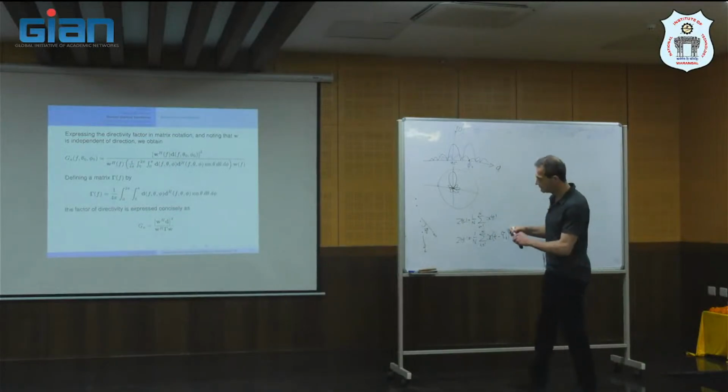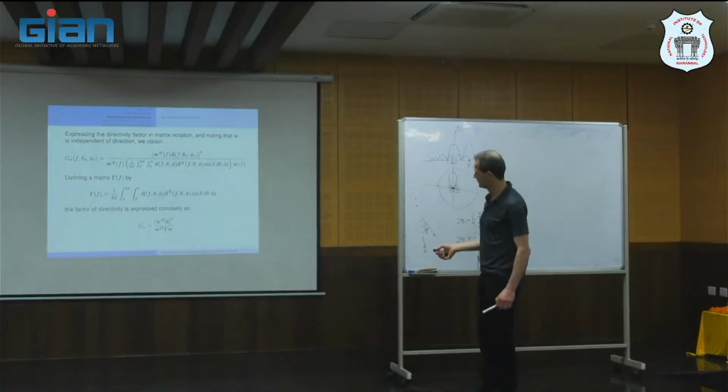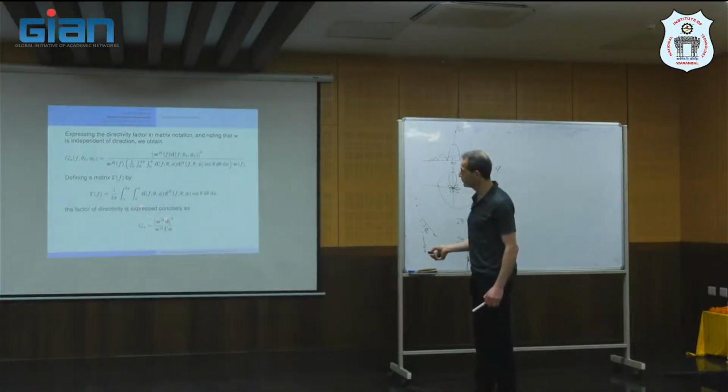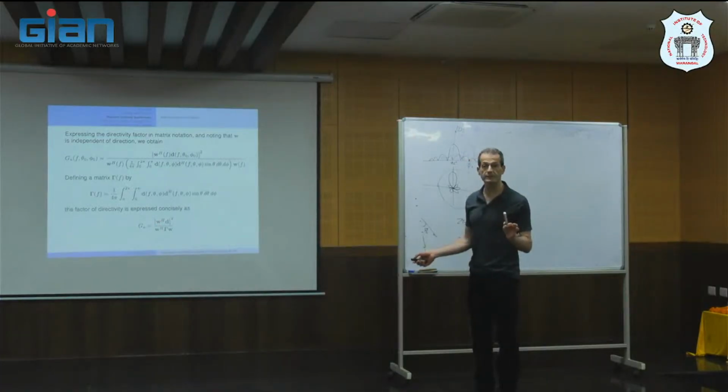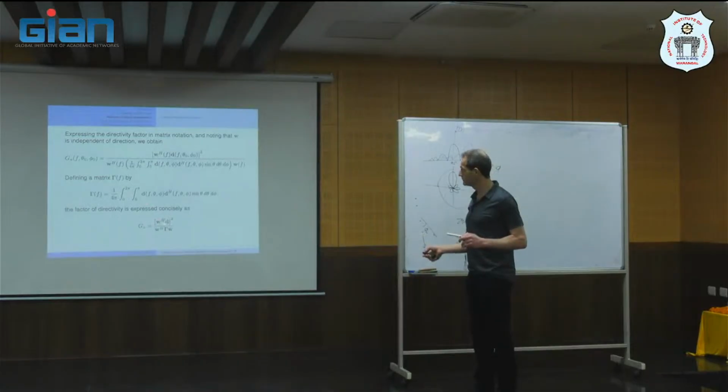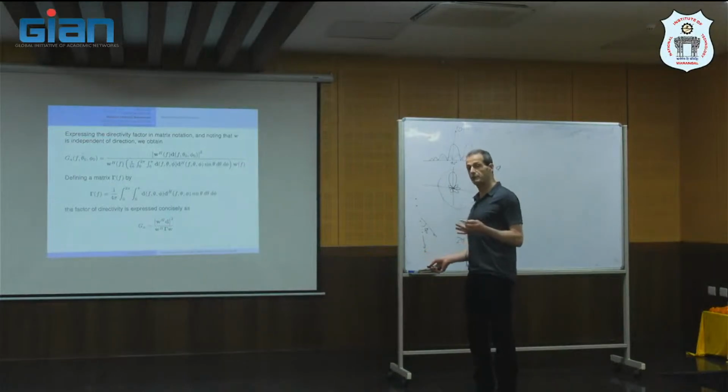Okay, so this directivity, you see that the numerator is the gain for the desired source, and the denominator, what is the gain for what? Diffuse noise. And we want to maximize this ratio for each frequency. We can do it independently for each frequency. Now, suppose that this ratio is high for a certain frequency. Is it sufficient? So it maximizes the directivity for that frequency.